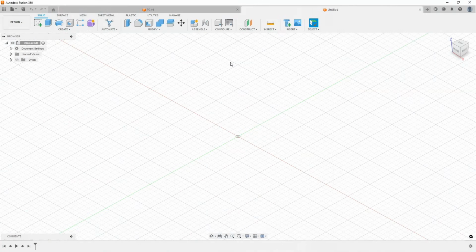In the previous lessons of this course, we discussed creating solids by extruding a sketch and extruding a sketch cut to create a 3D solid based on a 2D sketch and to cut a fragment of a 3D solid based on the 2D sketch. Another way to create 3D solids from a 2D sketch is to create a solid by rotating the sketch. Let's create a new project and create a sketch based on which we will create a solid.